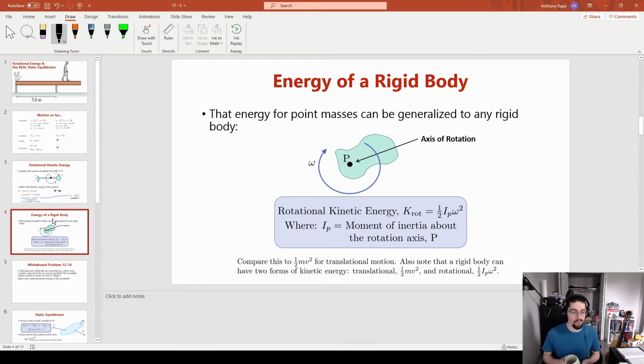All of these tools come in and start working together in a very nice way, right? You've got your table of all of these different moments of inertia, and if somebody says, I'm going to poke my stick through this spot rather than through the middle, then you can say, perfect, I don't even care. Right, all I'm going to do is take the parallel axis theorem. It's a really quick calculation. We've got our brand new moment of inertia. We can calculate the kinetic energy. We can calculate torque, angular acceleration, any of these things that we could possibly need.